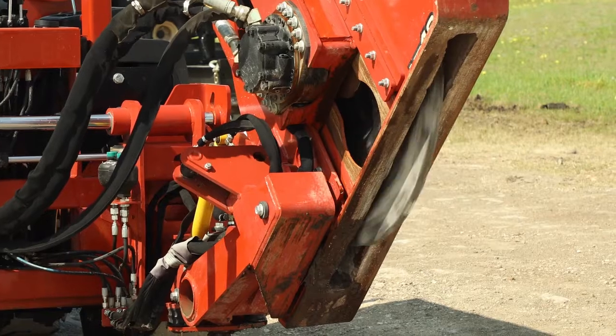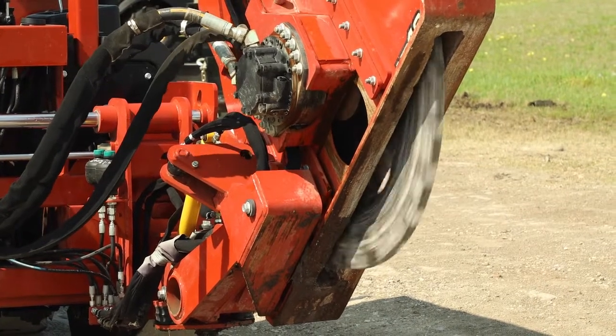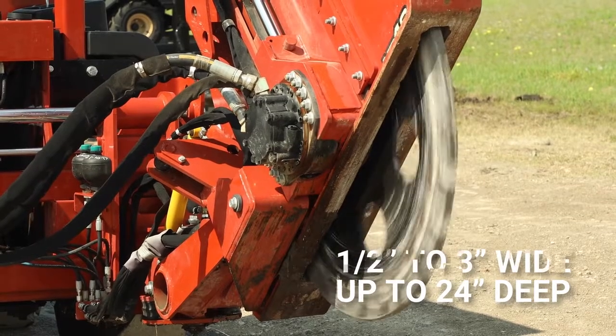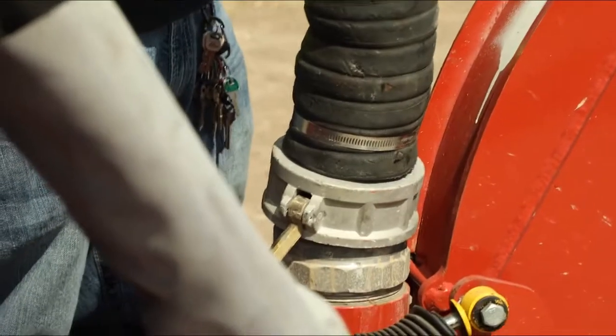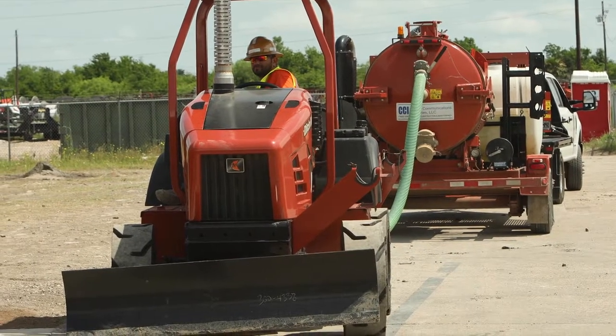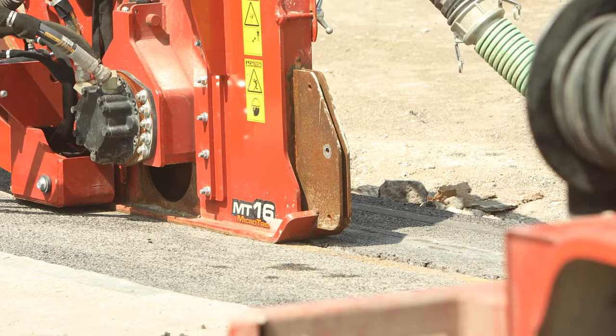The specially designed saw blade for cutting into asphalt, concrete, or rock cuts up to 24 inches in depth and a maximum of 3 inches wide. It is connected to a vacuum truck or trailer, which removes any spoils, dust, or dirt, creating a neat and tidy construction site.